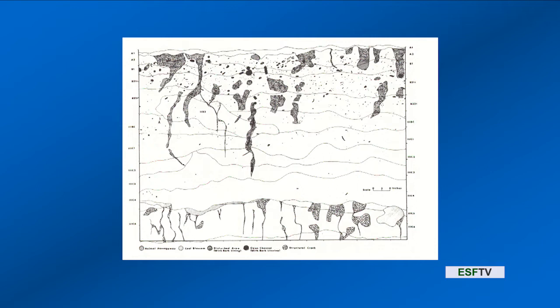These are pores that are large channels filled with organic matter, dead root channels, and this is in addition to just the macropores. These are large pores that are created by organisms. So about 30% of the soil. So you can see a rather phenomenal range, and so these are just loaded. 30% of the volume of that soil is loaded with these large pores. So it has really high capacity for infiltration and percolation of water. And as you go deeper and deeper, those pores dissipate. They become much less common, and Ksat goes down with depth.